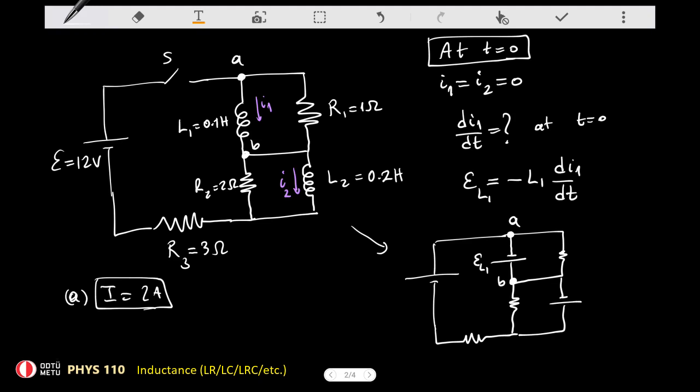So as a result, you can see that the potential difference between points B and A, if this was just an ordinary EMF device, I can express the potential difference like this. So I'm going to write it down like that. This is VBA. The potential difference, that's VB minus VA. That would be equal to the EMF. I don't know if this is positive or negative. Just keep this in mind. I'm just writing it by just looking at this expression in here, this picture in here.